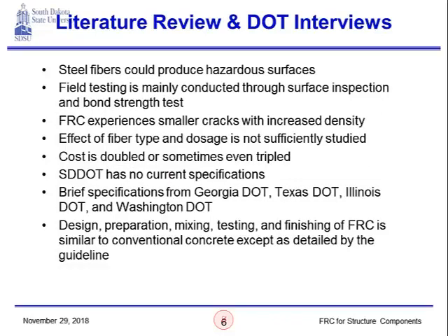Moving to the next slide. Steel fibers could produce hazardous surfaces, so this is something that we should keep in mind whenever we're using FRC with steel fibers in applications where pedestrians would be, basically, not for traffic, because this might cause injury, as the surface of the concrete would have some steel fibers protruding out from the concrete.